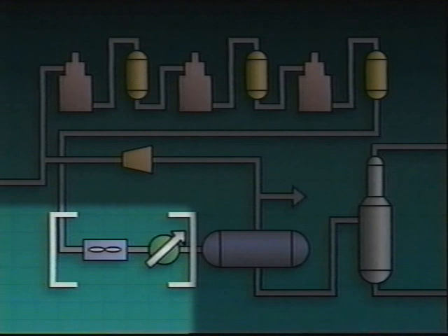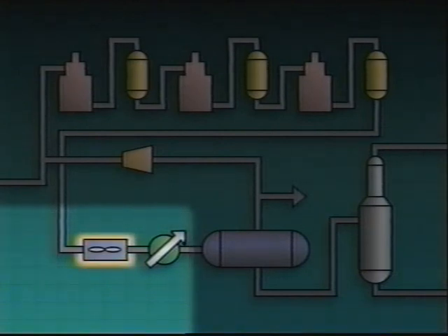A good way to proceed is by checking temperatures for these components. If either is too hot, it could result in not enough gas being condensed, which in turn results in a high hydrogen make flow rate. Since we've got two components to deal with in this section, we can apply some half splitting and check the outlet temperature of the fin fan condenser first.